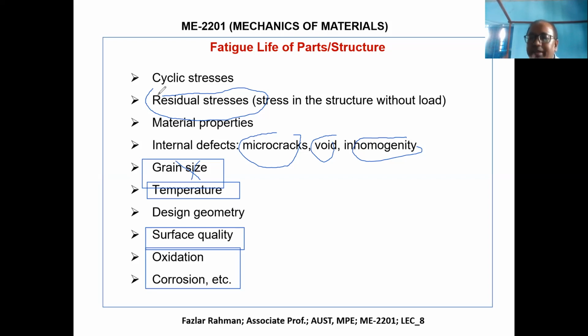That means you make it stress-free, then you put in your product, and there will be no stress inside. By mistake, say you are working in an LPG gas cylinder manufacturing unit, and you didn't do the heat treatment properly, and your mechanics say, go ahead, we can release this product. What happens? Inherently, the life will be reduced. You designed it for 10 years, but after 6 years it might explode.